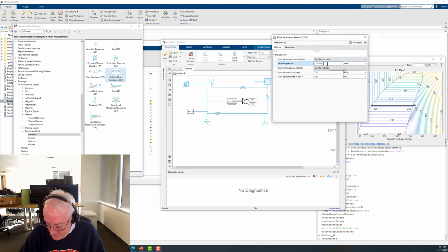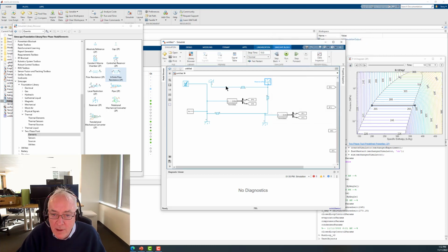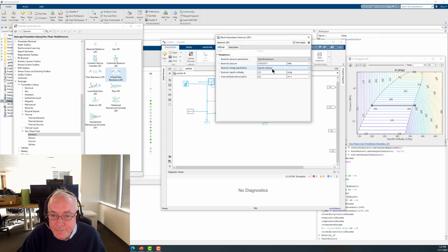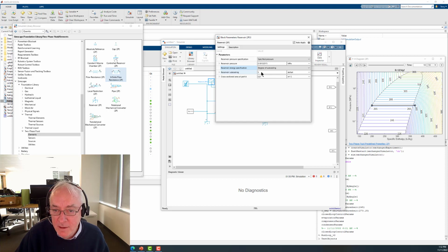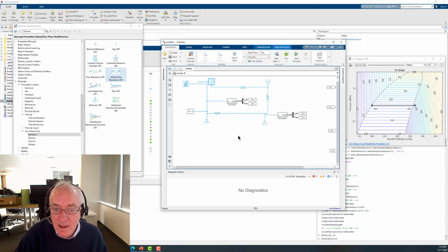And I think I'll have it go maybe like 10 times atmospheric pressure. I believe that here's where I found 400 was a good number to put in. Okay, and we'll need to do this one too. And here's something that I saw later in Aaron's tutorial that I really thought was kind of cool, this choice of degree of subcooling. We're going to increment it about 5 degrees to the left of the dome, but it will also be at that same pressure of 10 atmospheres. So I'll just multiply it by 10. And I think I got it.